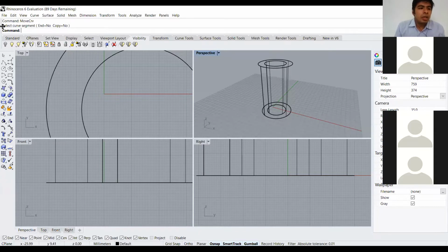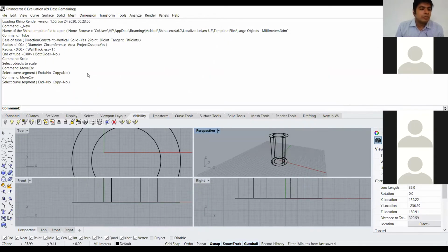About the history bar, you can just drag it down. It shows us the entire history, all the steps we had taken. For example, while modeling a complex geometry, or even a tiny detail like the grooves on a screw, if I've mentioned a radius for a particular command, or while filleting, and I want to know what that was, I can go into the history and check what commands I had used and what the steps were.